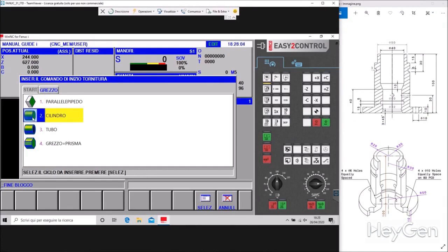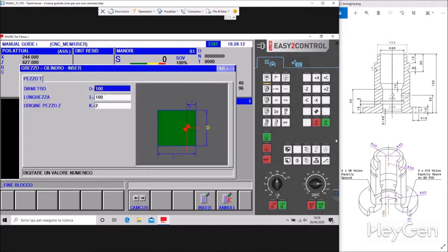They will start, for example, from a cylinder or a cut-off piece purchased from the supplier, full of the material requested by the customer. So we select the cylinder, and we've already seen this. We have an outer diameter of radius 50, so 100. Let's say we can take it here. We can do half on each side, and we've already made the external grip. We've worked the piece up to here, and we want to work on this area, so our grip will be roughly here. Let's ignore that we're a bit too cantilevered and focus on what we need to make the machine do.